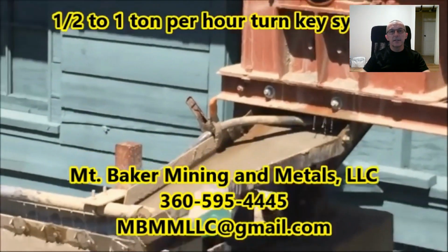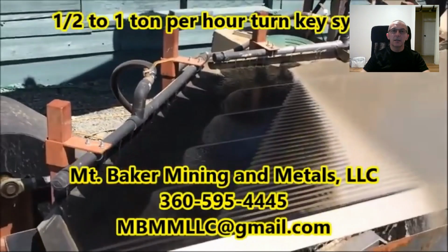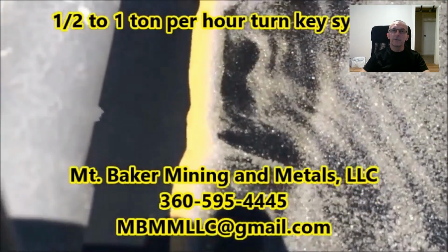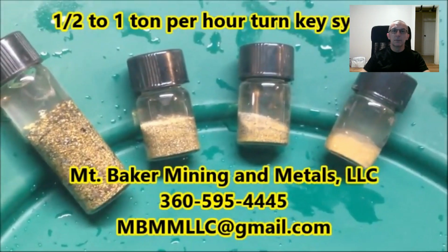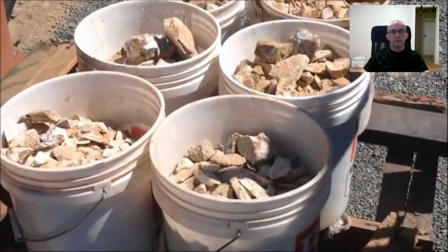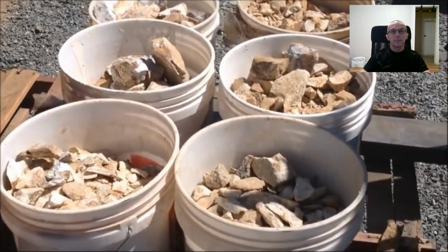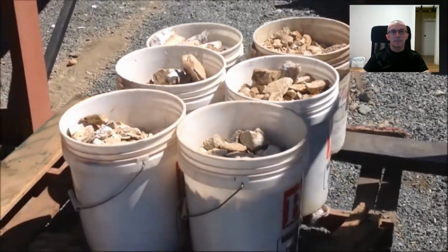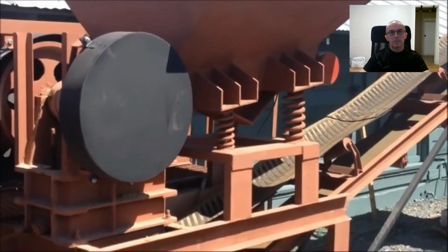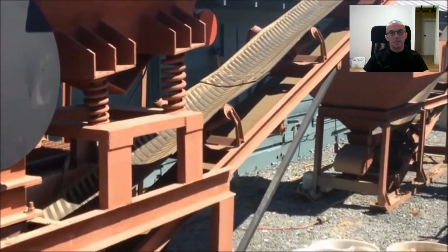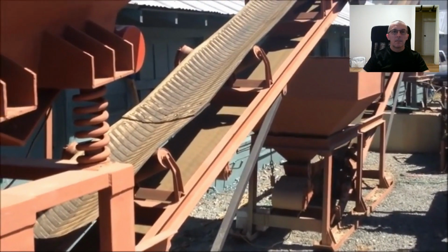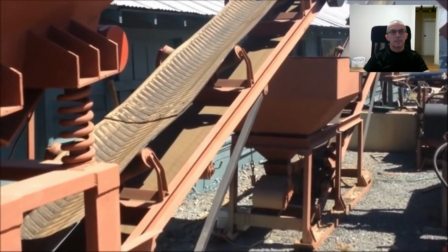So this is basically a machine that sifts the gold out of the ground. Today we're going to be running some high-grade gold ore that a customer sent up. We got about 300 pounds there, and we're going to run it through our turnkey system with the hopper and jaw crusher, discharge conveyor into the hopper, and another conveyor up into the hammer mill, and then onto our 4x8 shaker table.